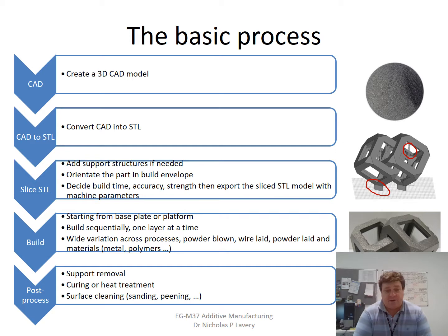Also, you need to consider things like polishing the parts to remove roughness, through sandblasting, shot peening, vibratory trough cleaning, all different types of cleaning. Then of course, what I haven't added on here, we'll also have the post-machining steps: drilling holes, possibly adding threads and all that sort of stuff that comes afterwards. So this is the basic generic process which underlies all additive manufacturing processes.